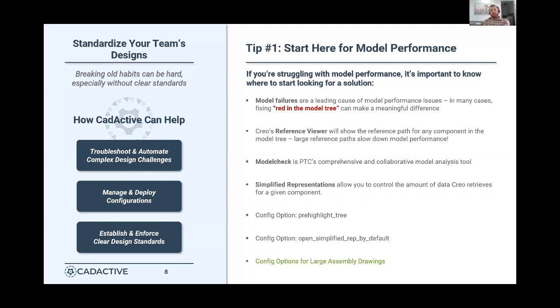First and foremost, there are a few things you can do right out of the gates without much upfront effort that can meaningfully affect model performance. Number one, red in the model tree. Errors in your model tree can happen for a lot of reasons, and very few companies understand the real impact that this has on performance at any level. If you can fix the red in your model trees, you're going to see an instant improvement.